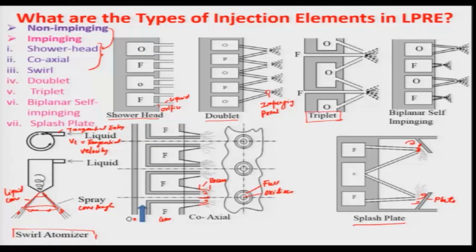And besides this, the other one which is being used for the non hypergolic propellant is that instead of impinging the fuel and oxidizer, the fuel and fuel can impinge together here, and similarly oxidizer and oxidizer, both streams can be impinging from the manifold of oxidizer. This is known as like stream impinging, and this is known as the unlike propellant impinging doublets.